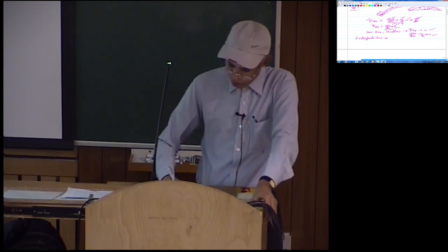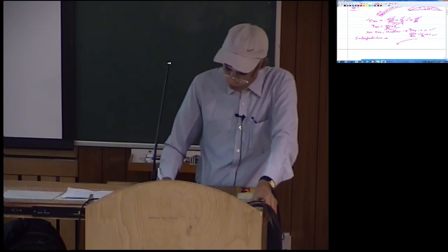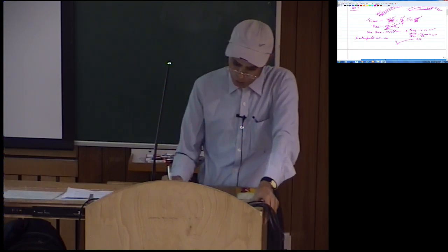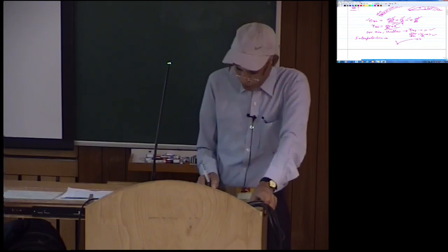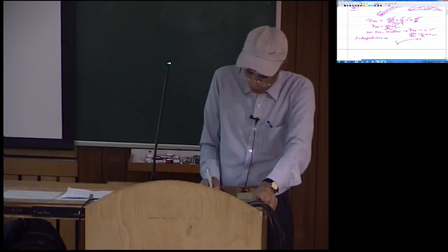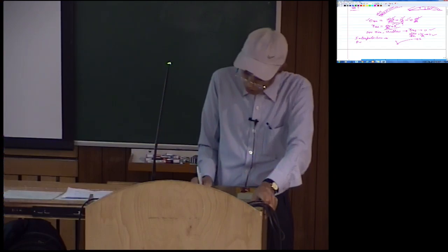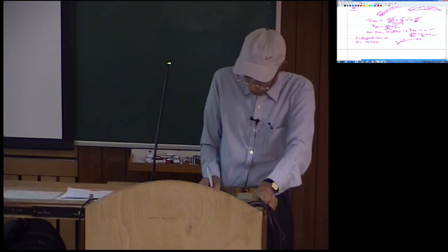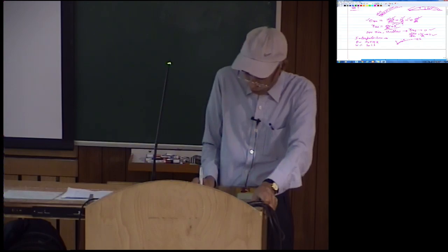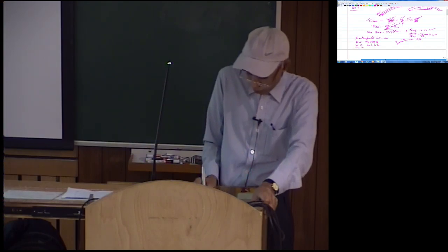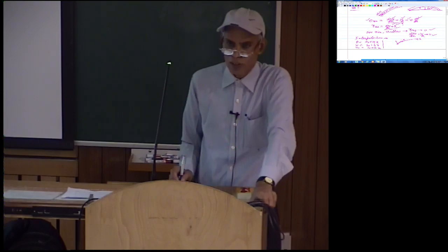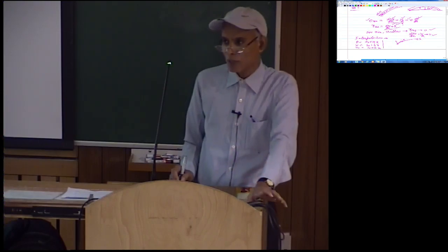That means the curved element can be, at minimum, a two noded curved element, node 1 and node 2, with each node having u naught, w and theta as the degrees of freedom. But if you look at theta, let me start with theta: a0 plus a1x, where x is the coordinate in this direction, and then w will be b0 plus b1x, and then u naught will be c0 plus c1x. But this is the minimum required interpolation of these field variables, and this will lead to locking.